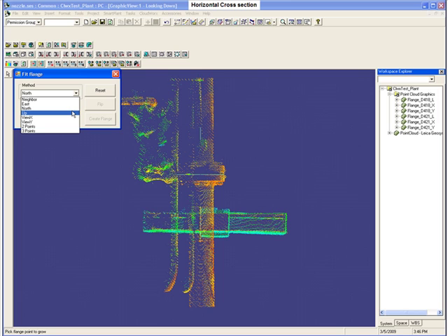If you have a lot more points, or a great deal of saturated points, you can use 2 or 3 point picks. These are the least accurate, and they actually try to region grow this flange in here. So I'm not going to be going over those, but go ahead and look at the documentation. The one I've showed you, neighbor, is by far the most accurate because it creates a center line off a nice straight pipe, and then you pick the back of the flange and enter the offset.